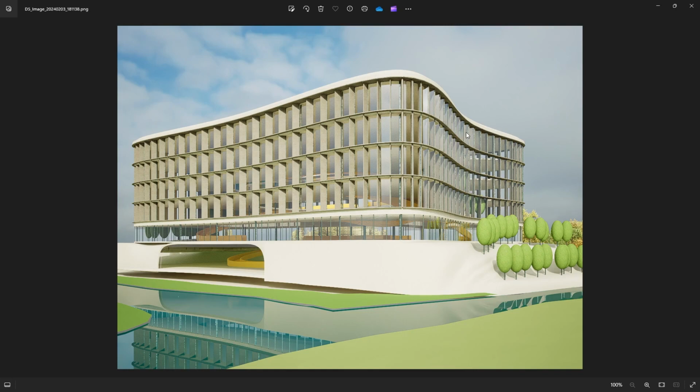So the glazing is facing north, because we're in the southern hemisphere, and the solid panels facing south, so that in the summer months when the sun comes over and goes low and very far past the east-west axis, you don't have that hot late afternoon sun baking into your potentially office space. So this facade was also a basic attempt at a little bit of climate control and solar radiation control.